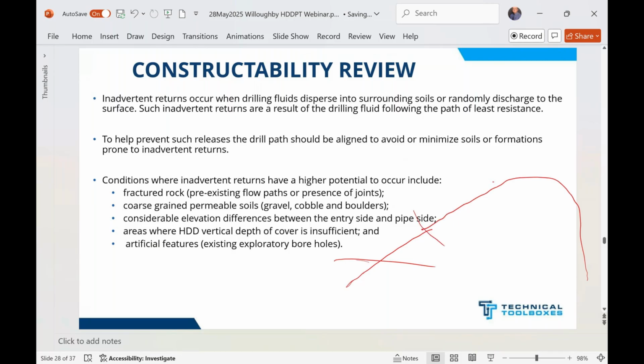The steeper this angle is, the higher he's got to pick that up to get down that hole, which increases your risk of stress. So the bigger the pipe gets, the smaller we make that angle. I'm talking steel pipe now. If I'm looking at a 16 or 20 inch pipe, I'm going to get down around a 4-degree angle just to make it easier to pick that pipe up and get it down that hole.